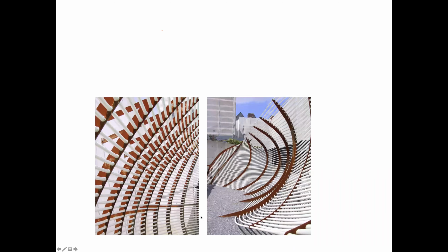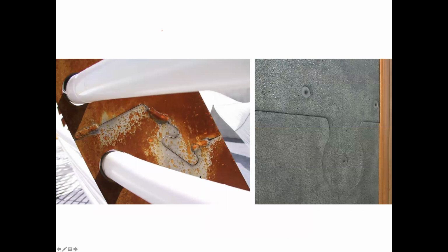But what's interesting here is these steel ribs. If you think about trying to nest those onto a flat sheet of, let's say, steel, and laser cut them or route them out, you'll have a lot of waste. So you break them up into smaller components that can be nested in a much more efficient way. But then all those shapes have to be put back together. When you look at this project, which was temporary and is no longer there, you would see that these ribs are actually a bunch of pieces put together with these puzzle piece joints, where you have, let's say, this length and this length, space for the welders to come in and zap it back together.